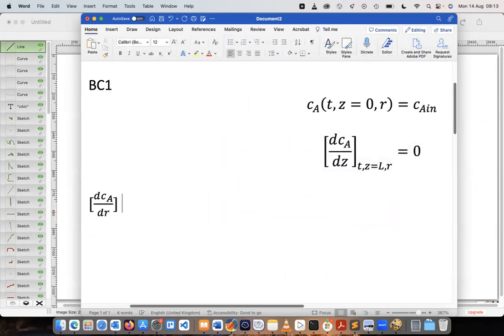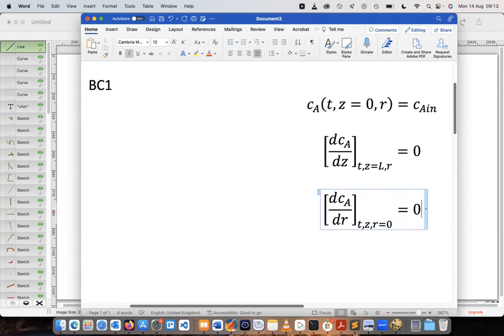Of course there are multiple locations of the center. That's more like a center line. So at the center line, in other words, at all instants in time, at all axial positions, but at the center line, r equals 0, then we have radial symmetry. So that's the third condition, radial symmetry at the center. Okay, any questions or comments on that?